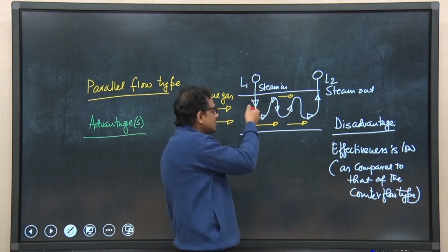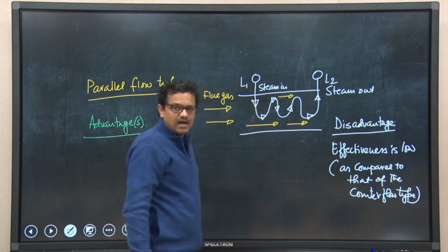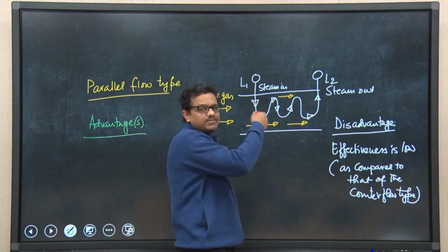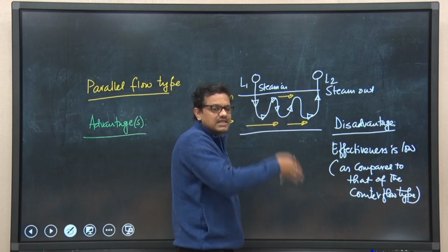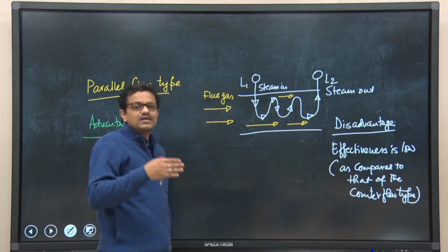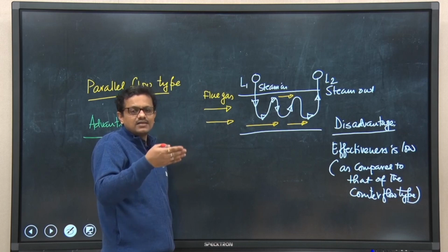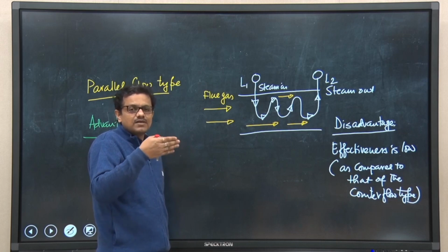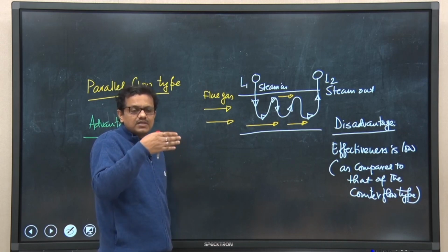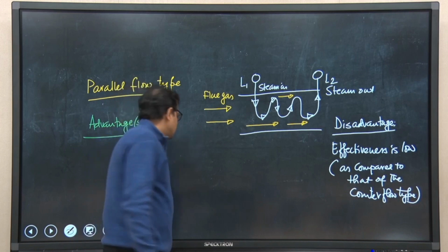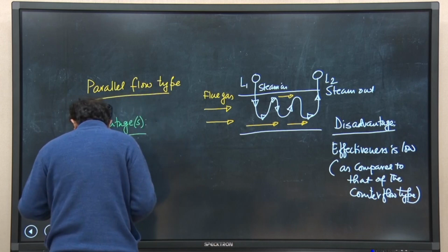It is quite expected that the outside temperature of the tube would be very high, but since the inner surface temperature is not that high, the problem which would arise because of the excessive temperature of the tube material will not be there.